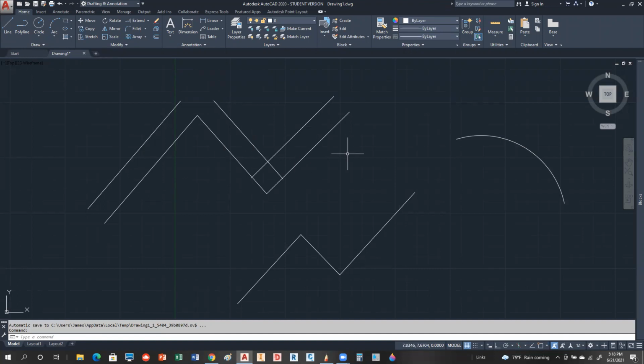And it makes a direct copy. So notice the endpoints of that line, copy there, and the endpoints of that. So these guys aren't coming together. Okay, so that's kind of a downside. And these guys aren't coming together either. In fact, they'd need to be trimmed. And we haven't talked about trim yet, so we couldn't really just erase that piece out of there, or extend those yet. In fact, I'm going to show you how to do that tonight. So there's kind of a downside when you're using lines.